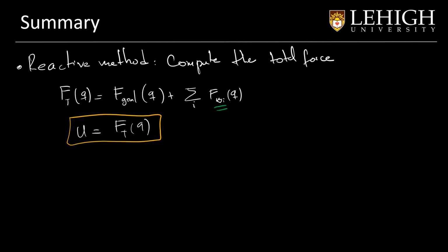Some of the advantages of this method is that it is very robust to noise and also to perturbations. Since the robot depends on the location, if it receives a perturbation and dislocates the robot, it will just compute the gradient from the new location, and it will not have problems to obtain that.